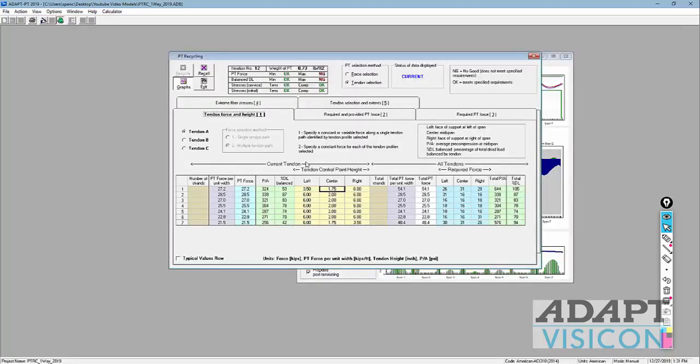And we're kind of back to where we were initially. We have some overbalancing. Maximum is no good in this end bay. It's 105%. Again, why is it more there than the end bay? Because that's the live end. This is the dead end. We lose force going from live to dead. This would also be most likely a workable design as well. We have a little bit of overbalancing.